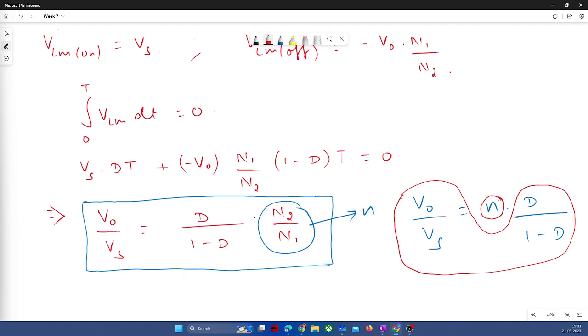Do you know the specific names of the controllers which have this type of control? Because the 3842 and 44 series are fixed voltage, fixed frequency PWM controllers, but the current mode controllers have both frequency as well as PWM. If you know, please suggest us. Definitely. As of now, I am not able to recall the name, but I will look and I will tell you the name of the controller in the next session.